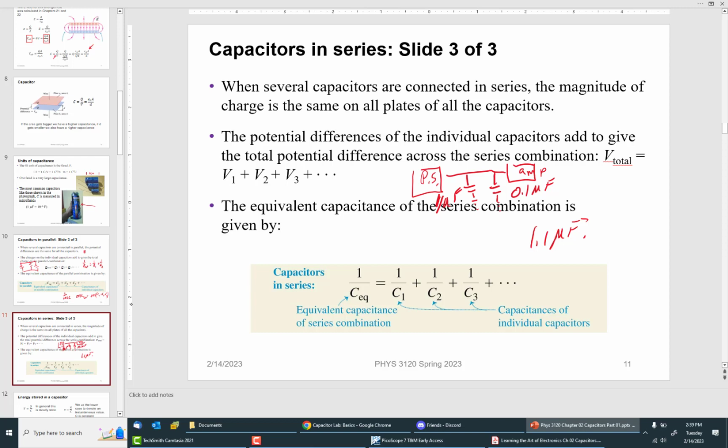If you look inside any circuit boards now, or a computer motherboard near the CPU, there are these little tombstone-y things. They're all capacitors, and they're all there to get rid of ripples, because you want the square pulses, the ones and zeros, to come through without noise.